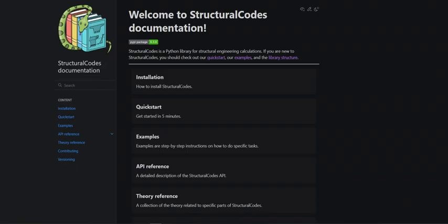But, broadly speaking, the big difference that I found between Eurocode and ACI is that there's more variability in the different types of partial factors that you can use in Eurocode. You've got a broader range of specific safety factors or material factors that give you a bit more flexibility to create the most efficient design for a specific purpose.